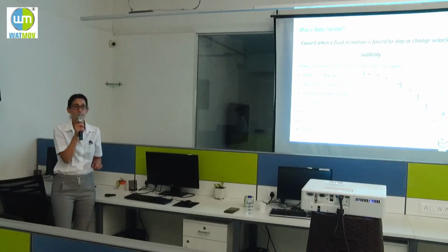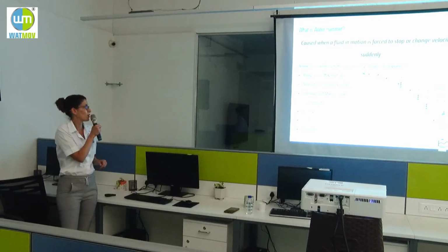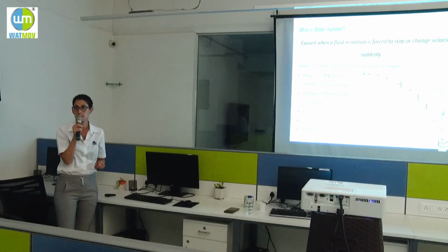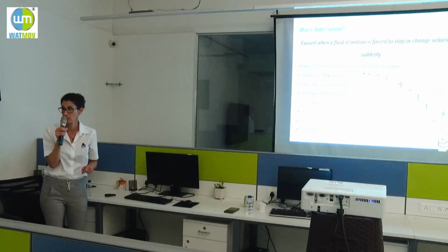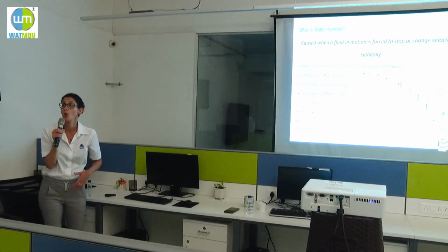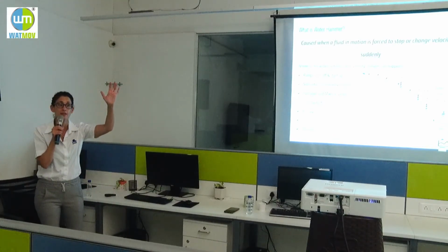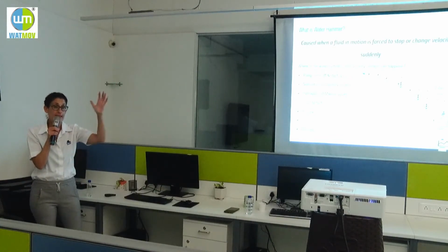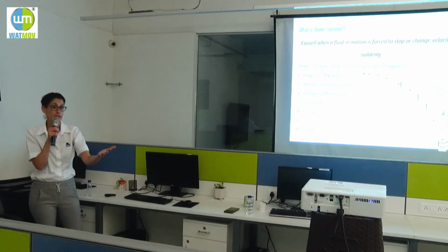Hydraulic and manual valves, okay? We don't want them to close too fast, okay? And create a surge. Air valves, okay? If an air valve releases the air too fast, it can cause a slam and create a secondary surge.